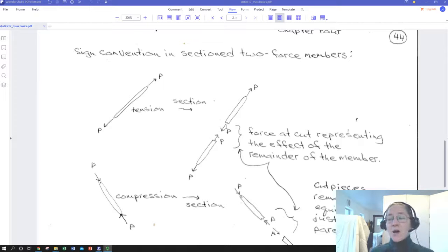And in fact, that's the law we invoke to model those internal forces when we make that virtual cut. But if you're ever lost, just think, I make a cut and I have to keep both cut sides in static equilibrium. So what forces, moments, etc.? In the case of a two-force member, it'll only be one force and it'll be collinear with your original line of force. What will have to be applied to keep my cut section in static equilibrium? And that will help you understand exactly what force is being applied internally.